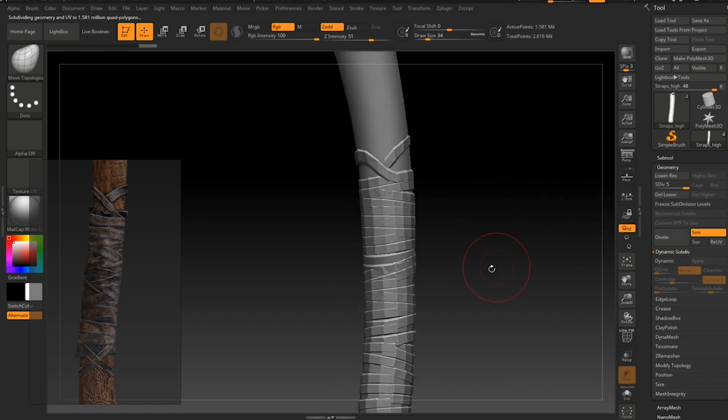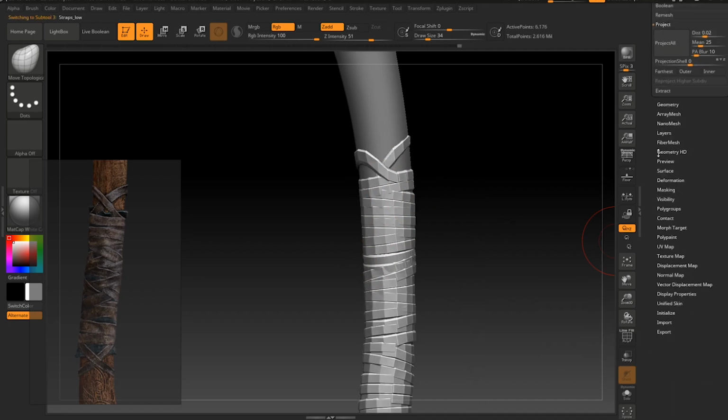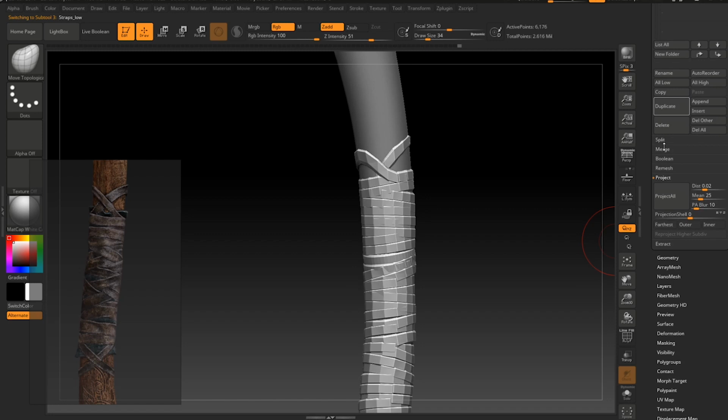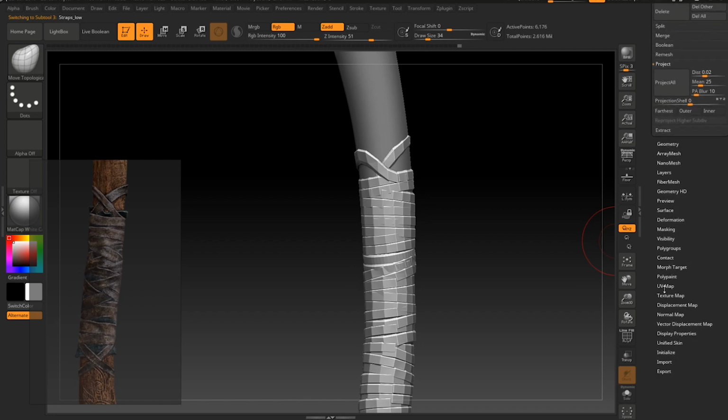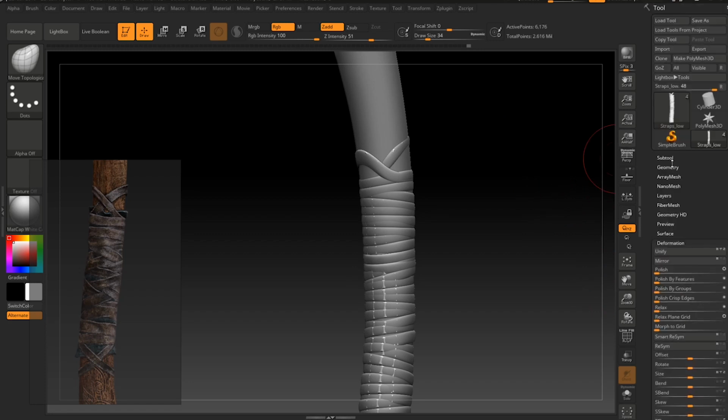And if we go to solo mode, you'll see that the low poly is kind of taking front and center here. So let's just go to subtool. Let's go to our low poly. Low poly, we'll go to deformation and then we'll inflate by minus 0.1. Did that do anything? Minus 1. Okay, so I would like us to now check the effect on the subtool.